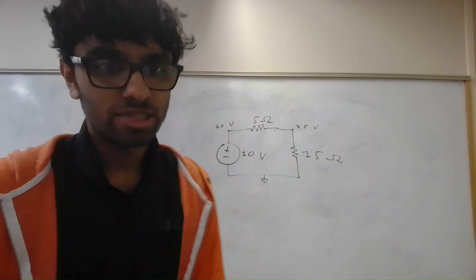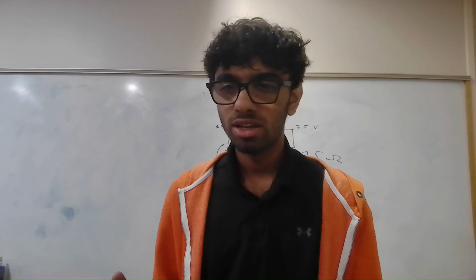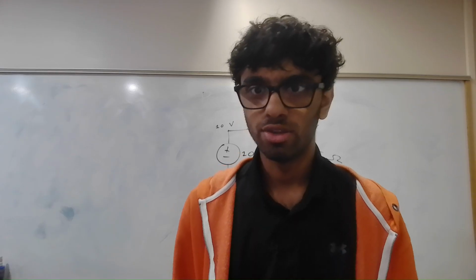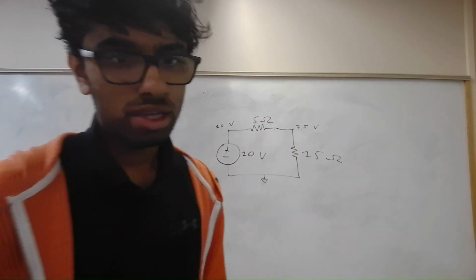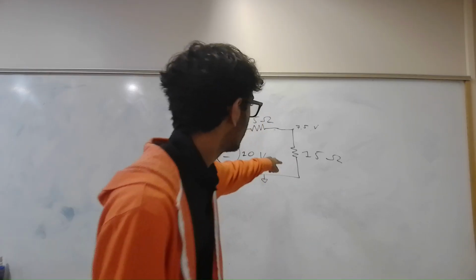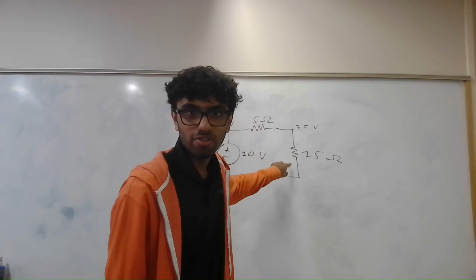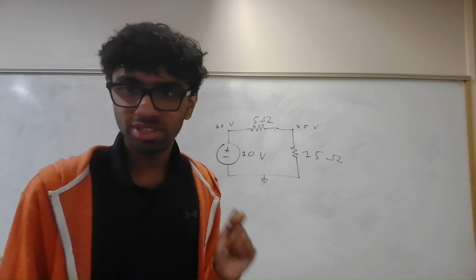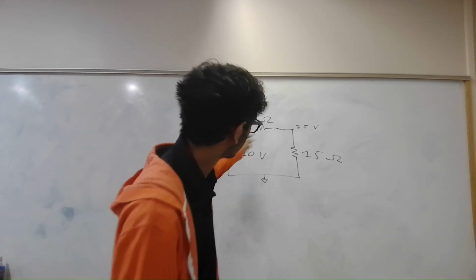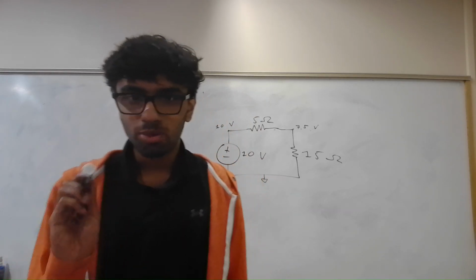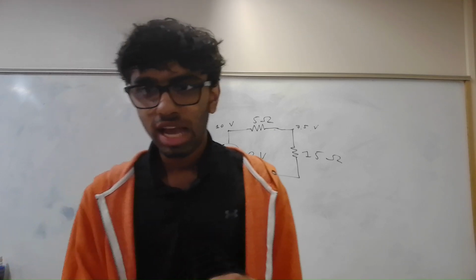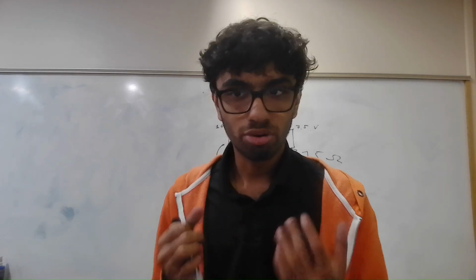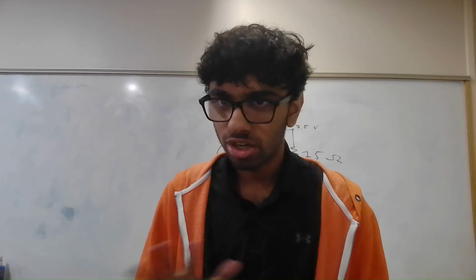The purpose of this question is to say, suppose I wanted a device that measures the voltage, that measures the current. How do I construct this device? How do I use that device? Based on the fact that if I change the resistance of R1, or rather, change the resistance of anything in the circuit, I'm going to change the current that's flowing in the circuit. And so if I want to use a device that measures current, I need to not change the resistance. So this device that we add in, a good property it should have is that it shouldn't change the current of what we're measuring.